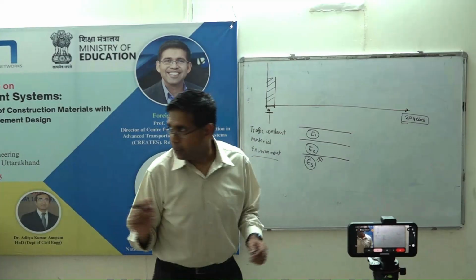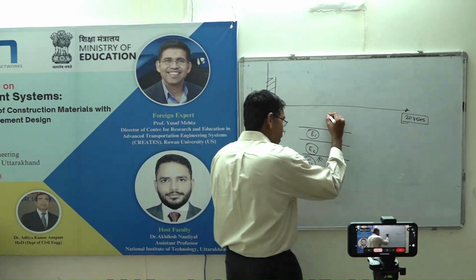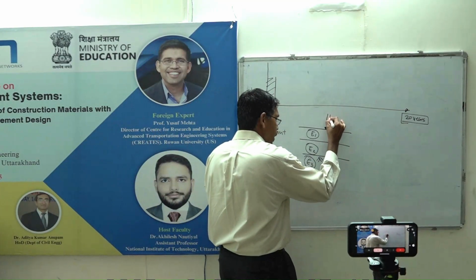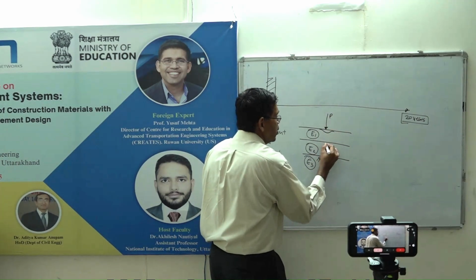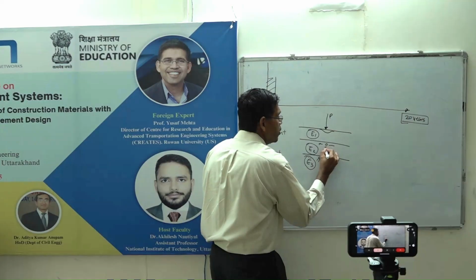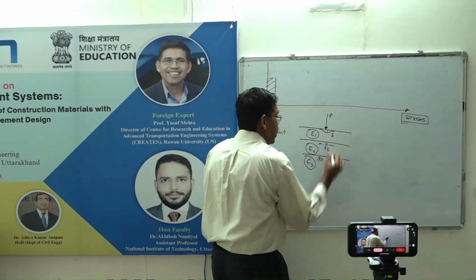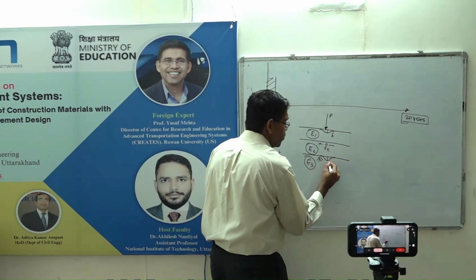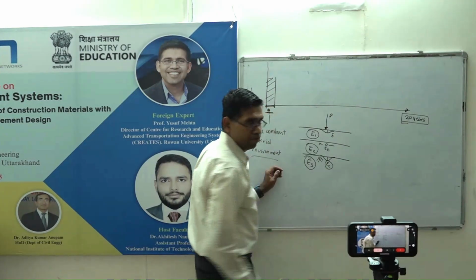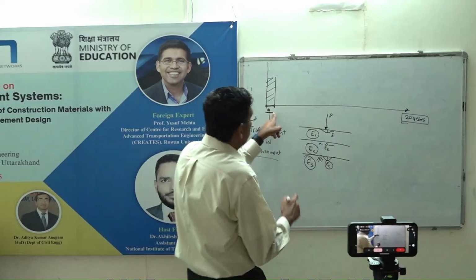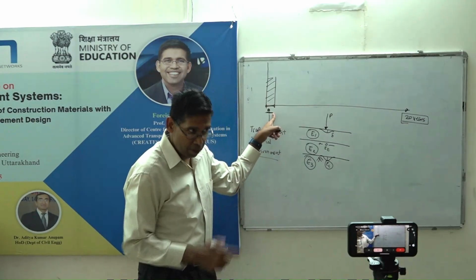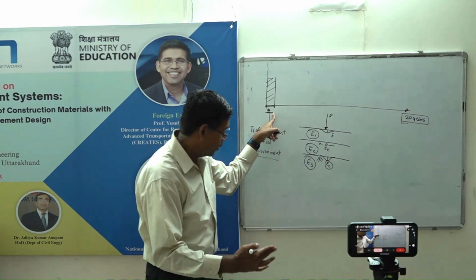This is what happens. You apply the load, right, at that particular time. You calculate rutting, tensile strain. This is delta. And then you calculate epsilon C. Correct? You do that for the first 15 days. Remember, you keep it constant.